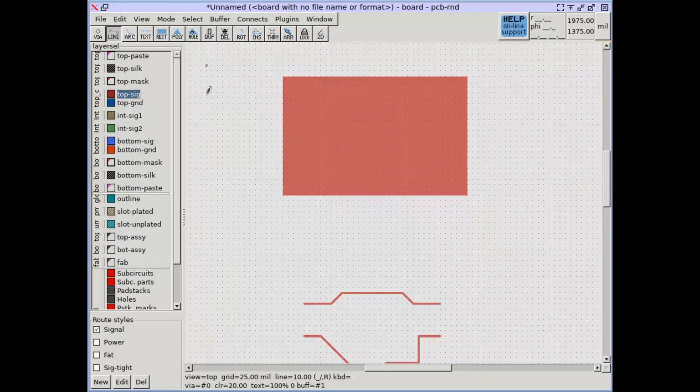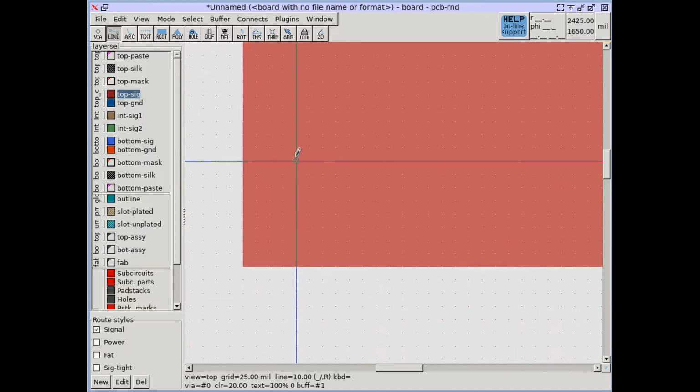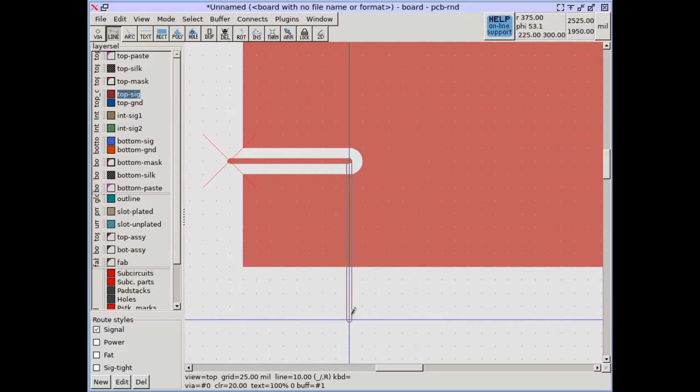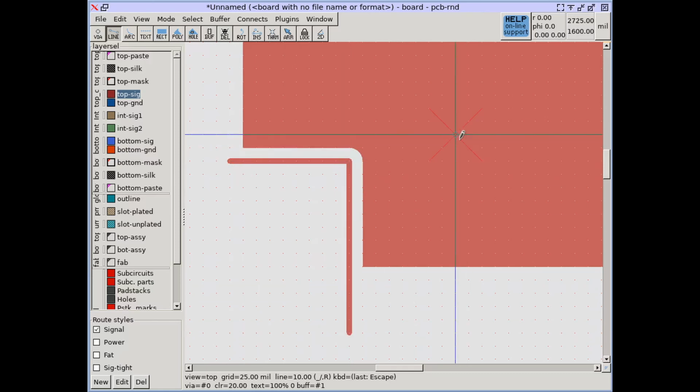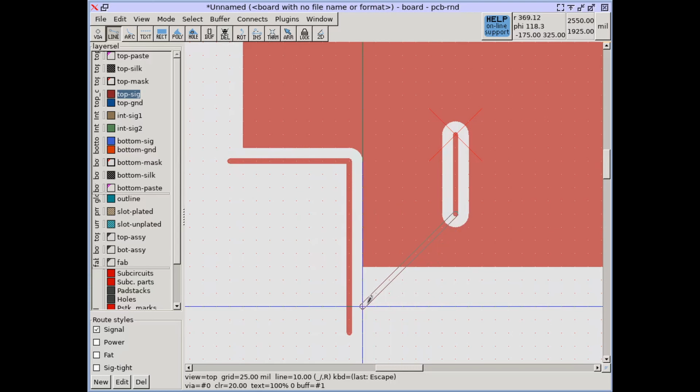At the end of the day, an important metric of board validity is that the gap between two nets is larger than a minimum value. This gap is called clearance. When a trace is drawn within a polygon, this clearance is normally enforced by the polygon code as a visible cutout from the polygon. However, other trace lines are not cut into.